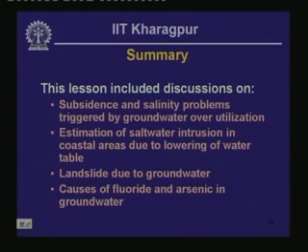Now we have come to the end of this particular lesson. We want to summarize what we learned. We have looked at the issues related to groundwater overuse, such as subsidence and salinity problems. We looked at a simple procedure for estimation of saltwater intrusion in coastal areas due to lowering of water table, how much you could lower the water table before saltwater ingress could be a problem.